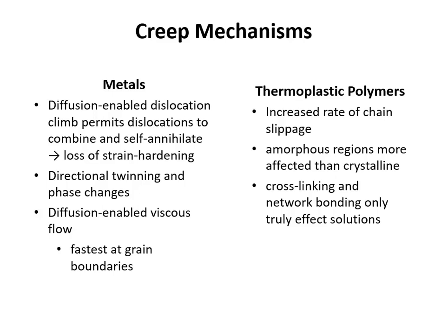Again, diffusion can also be described as effectively viscous flow. It's another way of macroscopically describing creep-based deformation in metals, irrespective of mechanism. We can assign effectively a creep modulus or a stress relaxation modulus to a metal, just the way we did with viscoelastic analysis of polymers.